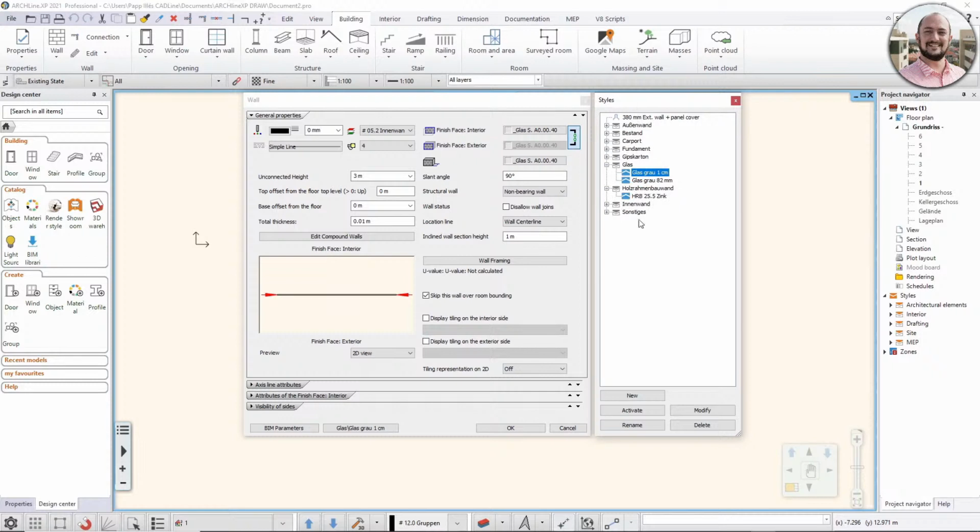So this is how I cleared it up, and whatever I saved in my specific project and in the template itself, all the styles of the doors, windows, columns, beams, slabs, and any other item that supports styles are saved into my template.